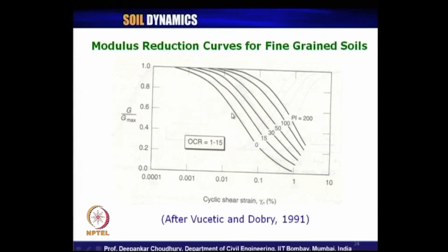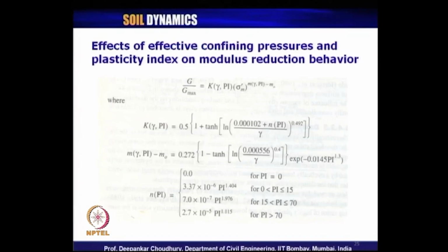Later on, several researchers, like Bray et al., pointed out this mistake, that this is not the correct graph only for PI equals 0. So, whenever you are using this graph for your design or analysis, make sure that you are not using the line PI equals 0, but the other graphs are correct. So, that is why the limitation of any particular test etc. must be known rather than using these curves blindly for analysis or design.